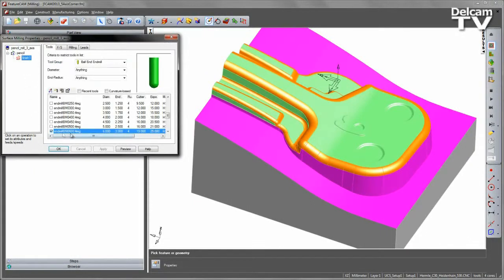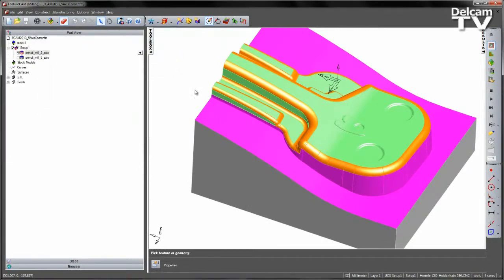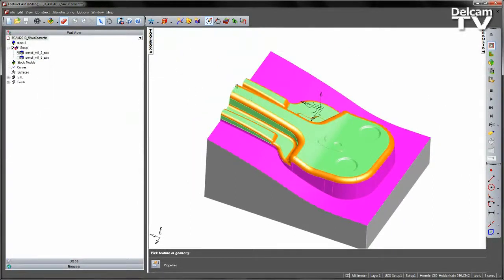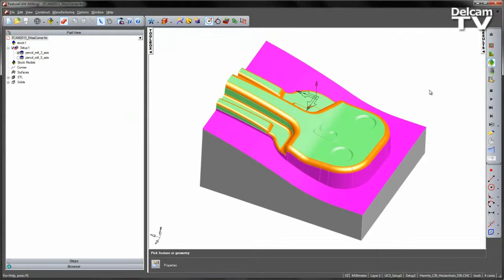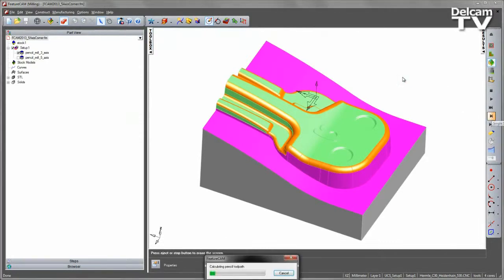If I go to the tool size, you can see we're using a 6mm ball nose. This is the standard tool available in the metric tool crib. So let's have a look at the simulation. I'm just going to go into a 3D simulation. Just do a single step first of all to establish the toolpath.